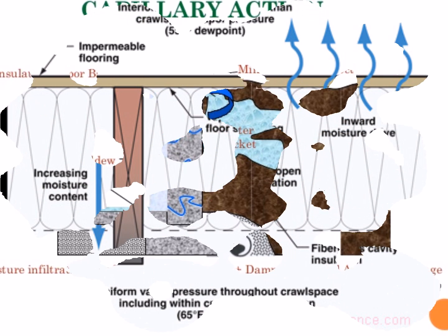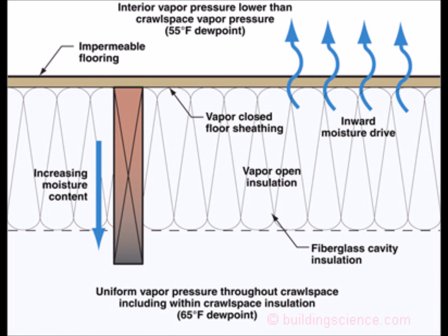The house must be able to shed water from the roof to the footing. The roof is not waterproof but water resistant. It's designed to take the rainwater away from the house. The roof must work with the gutters, downspouts, as well as the exterior wall covering. These different components must be matched in order to work together properly.